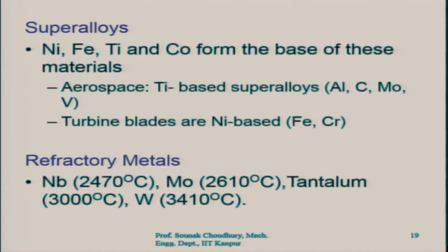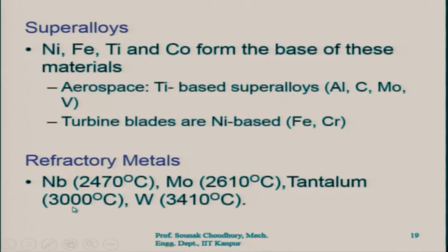in the furnace where you melt, where we get the molten material. We prepare the steel, alloys, alloying materials, alloy steels and so on. So, there the temperature becomes very high and we cannot have any loss in the temperature. Therefore, inside those furnaces there is a layer which is made by the refractory metals, and the refractory metals should withstand very high temperature. You can see that these materials actually can withstand really high temperature, which is beyond the melting temperature of many metals.